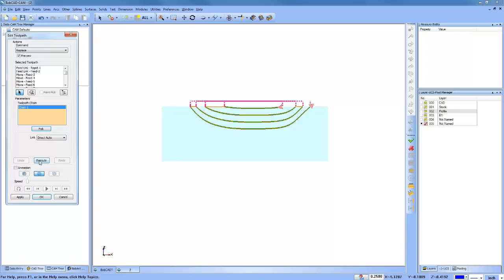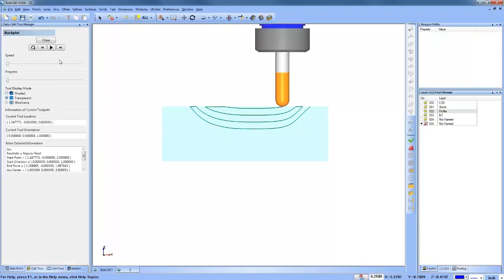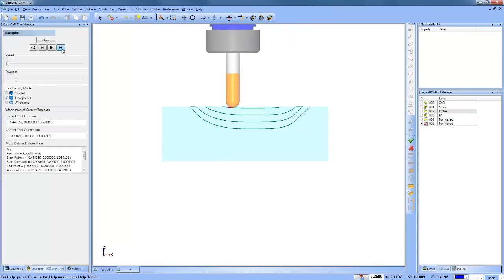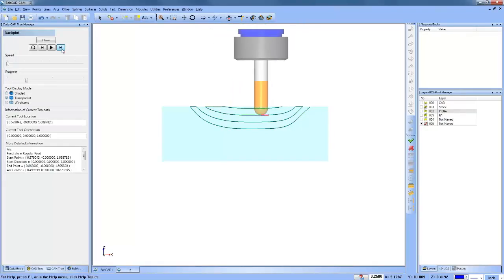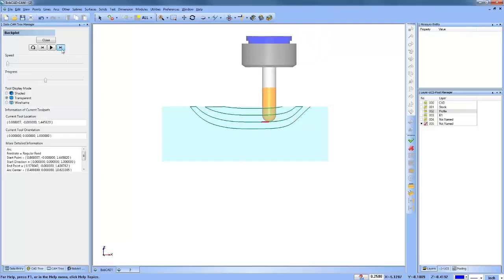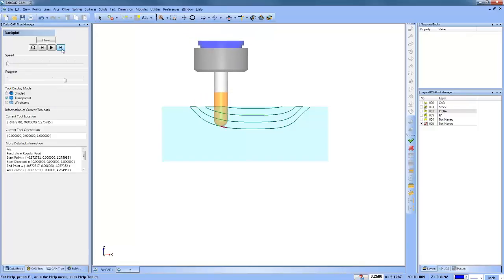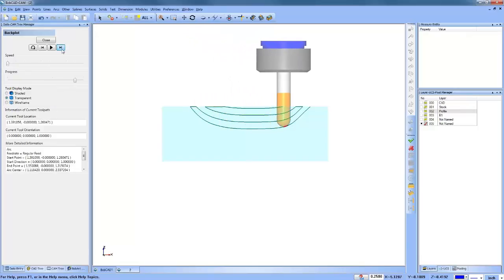We're going to go ahead and choose execute, and then OK. So this is an example of how we trim down our 3D wireframe toolpath, and then also turned it into a zigzag in order to work its way to get down to the bottom. Okay, so this is, again, another way that you can use the toolpath editor. This is the replace example that I have.